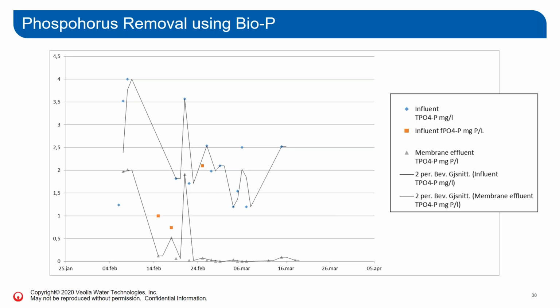We're not able to hit the very, very low concentrations of phosphorus that we can hit with physical chemical precipitation. But we can reliably accomplish 30 to 40% removal of ortho-P through the biological phosphorus process. And that will obviously be directly transferred into your operational expenses by reducing them by the same amount you would be removing using the bio-P.